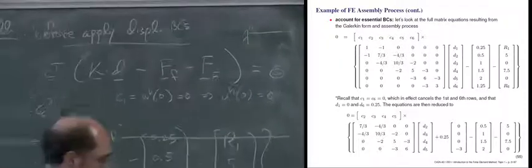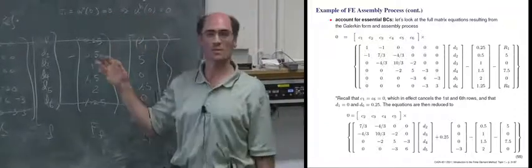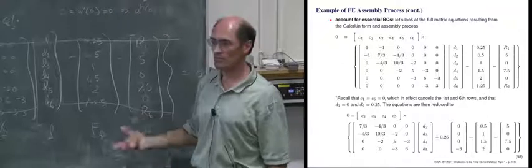And the weighting function, you can think of it like a virtual displacement or a variation on the displacement field. So any perturbation on a known quantity is 0. That's what variational calculus or virtual displacement concepts from energy methods talk about. So in a weighting function sense, the weighting function must be 0 wherever this is prescribed. Okay?